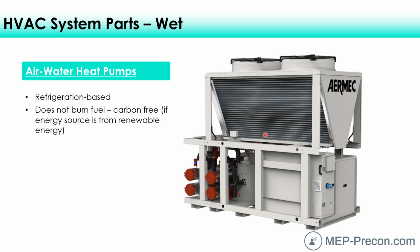So that's where the trade-offs need to happen that HVAC engineers think about: can we use this for part of the year perhaps? What's getting pretty popular now with the phase out of carbon and natural gas is to use perhaps an electric air-to-water heat pump to provide some heating water. But when it gets really, really cold, you would just use a straight electric boiler, because at that point that's going to be more efficient than an air-to-water heat pump, because these are just going to fail to pull the heat if it gets really, really cold, depending on the manufacturer. But if it gets down to 20 degrees, 10 degrees, yeah, it's probably going to make sense to have an electric boiler for backup that way.